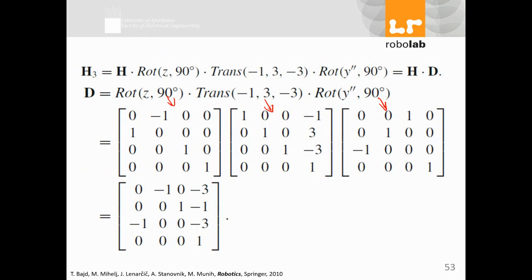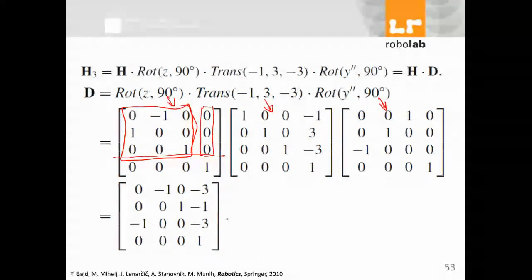For a 90 degree rotation, if you remember, there is no linear or translational move. Again, you remember that this part is part of the matrix and your rotation will be reflected in this part. Depending on whether you rotate around Z, X, or Y, and with what angle, you will get different values here. So I have rotation 1, translational move, and rotation 2. When you multiply them together, you get this matrix. So this matrix is this part.